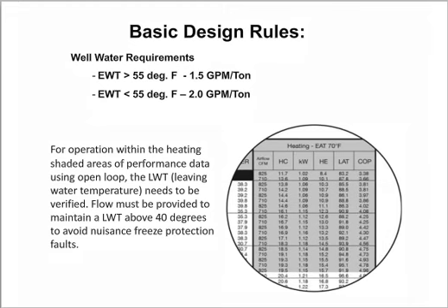And again, if you're starting to flirt with that 40 degree temperature leaving the heat pump in the heating mode, then you want to elevate that flow rate to make sure that you maintain that leaving water temperature a little bit above that 40 degrees, because you don't want to keep going out, nor does the homeowner want to have these little red lights turning on saying there's a problem. So make sure when you're doing a startup on a pond loop system that you are in fact paying attention to that. That's part of good startup procedures for any technician.